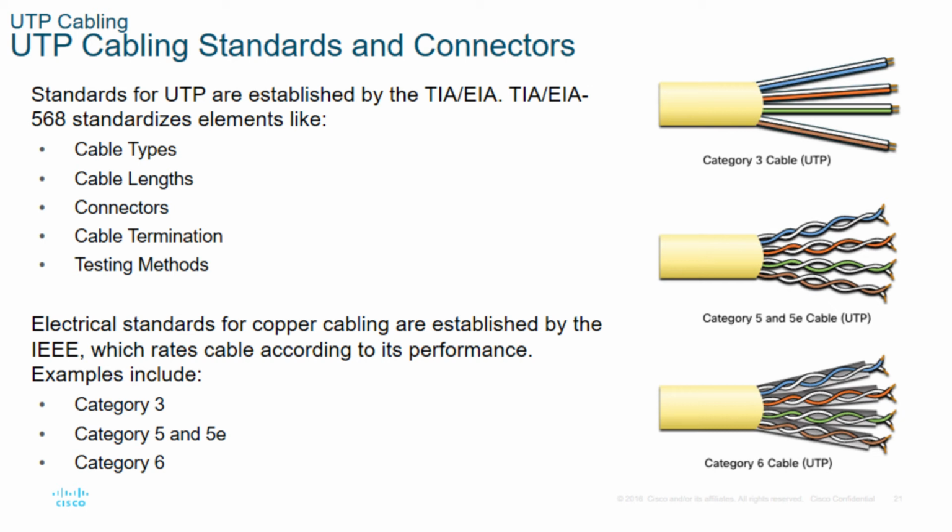For example, Category 5 cable is commonly used in 10BASE-TX and 100BASE-TX for Fast Ethernet, and other categories include enhanced Category 5, Category 6 and Category 6A. Cables in higher categories are designed and constructed to support higher data rates as new gigabit-speed Ethernet technologies are being developed and adopted.